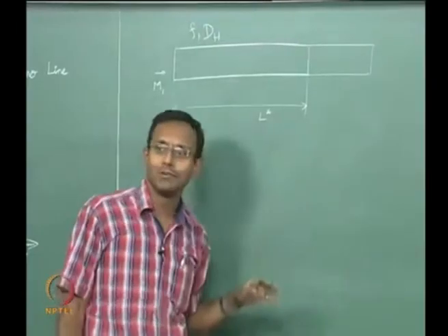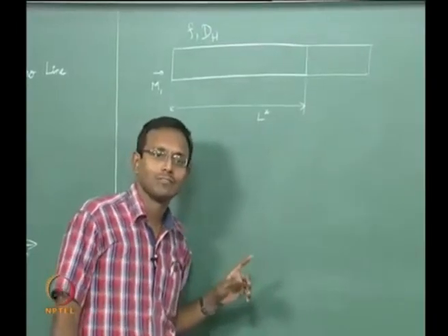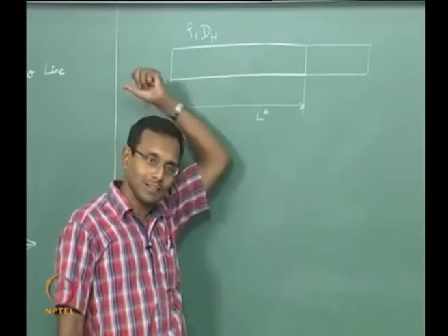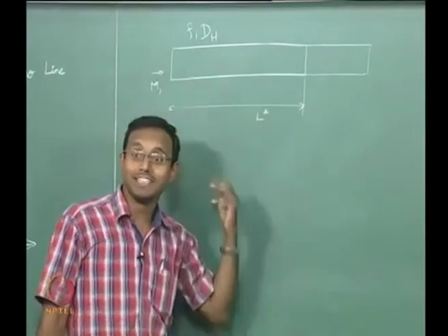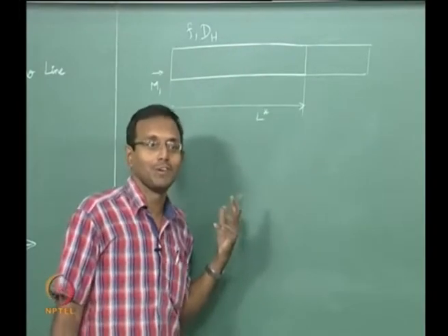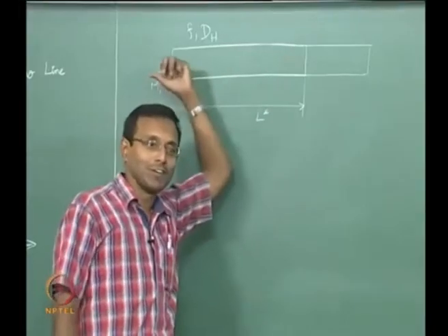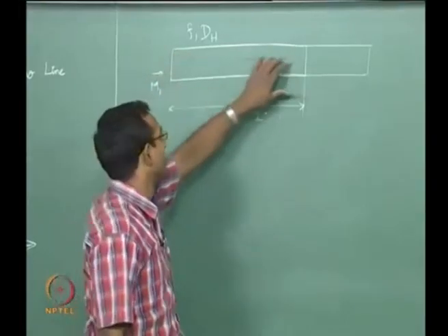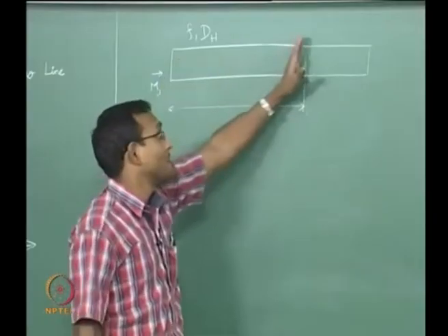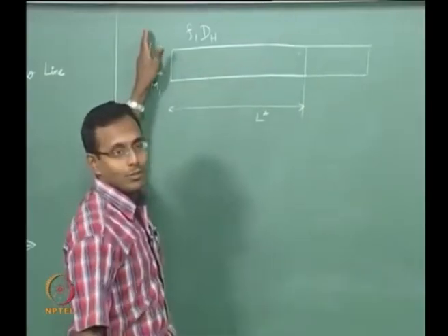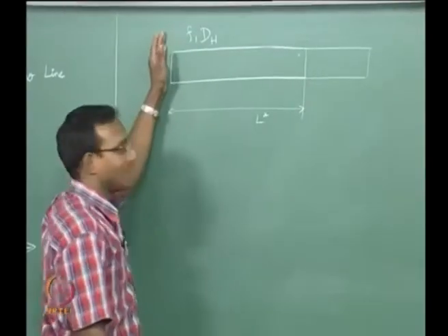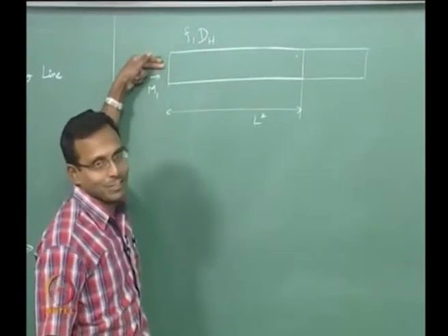What will a compression wave do to a subsonic flow when it is traveling this way? It will decrease the velocity, right? Compression waves are going to tell, don't go there, come this way along with me, right? So it is going to decrease the velocity and it will keep on going in all the way to a point where it will go to the front and change the inlet velocity here.